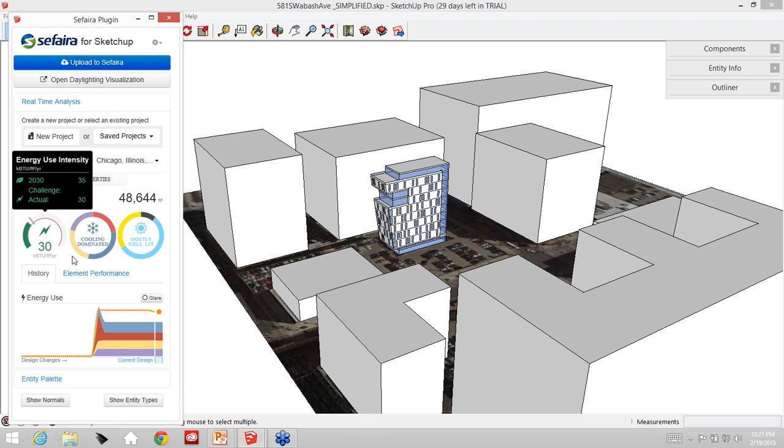This first one is giving us an understanding of energy use. Specifically, it's expressing energy use from an annual standpoint and as it relates to square footage. So that's where that 30 number comes from. That's related to annual use and square footage. The reason we do that is because it compares well to an industry standard benchmark known as the 2030 Challenge benchmark. If you're unfamiliar with that, that's an industry effort to get building energy use down to zero by 2030.